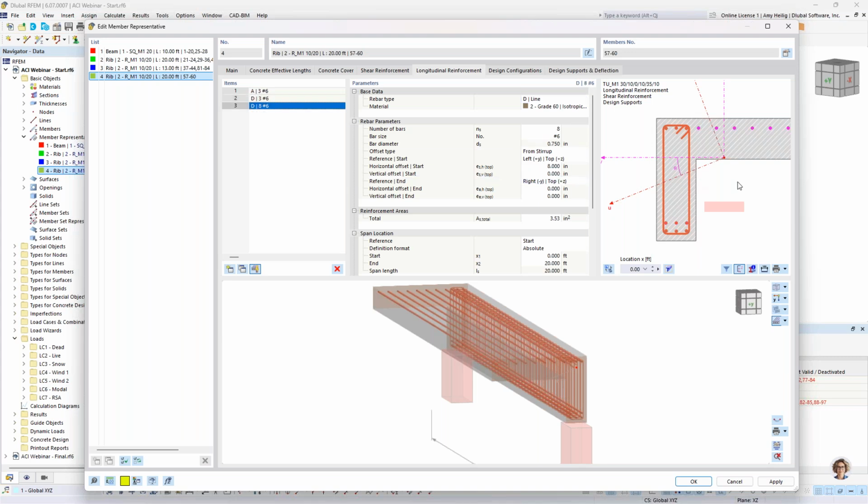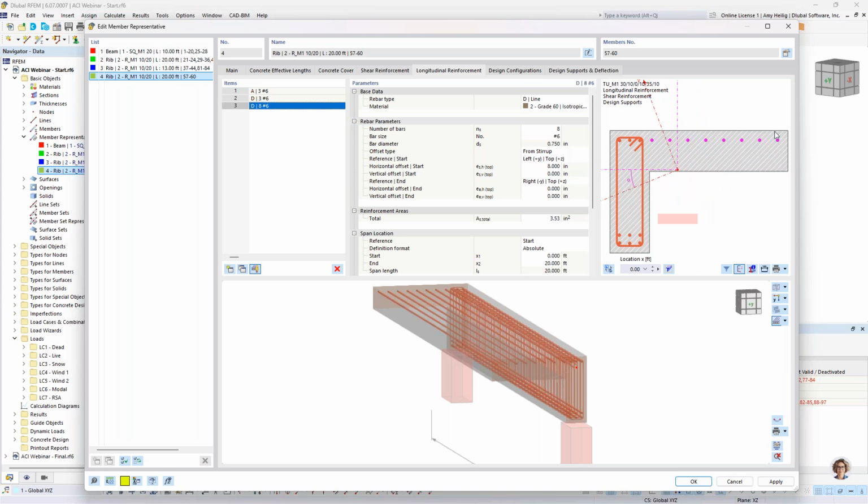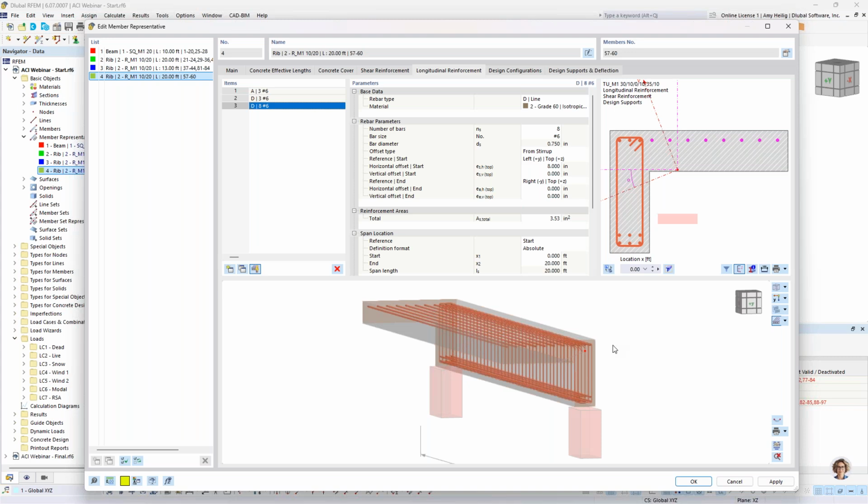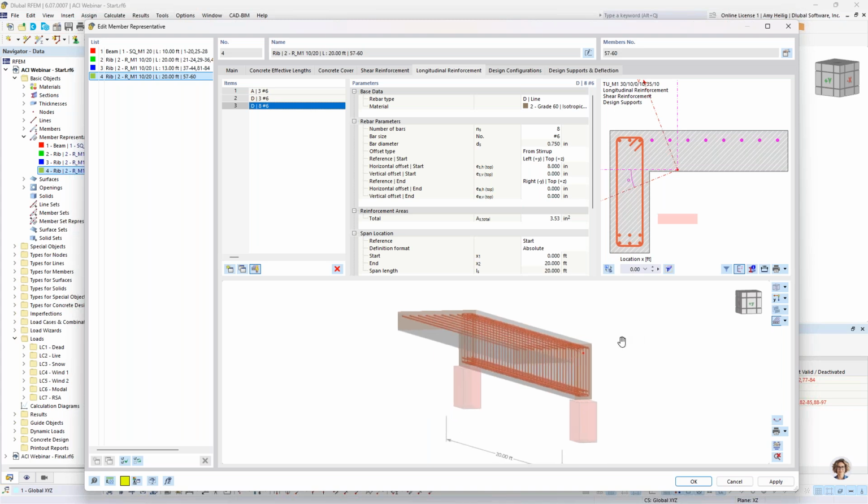And finally, we have 8 number 6s that are defined in that surface effective width itself. So this was also defined with the line option. I modified the offset here, such as 8 inches, so that we can input in this longitudinal reinforcement within the slab element. So pretty simplified for today because we'd probably want to create different zones with different longitudinal reinforcement, but this is just a little bit of an overview for this simple example.